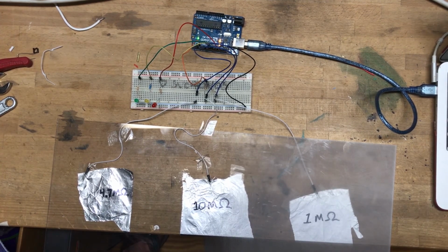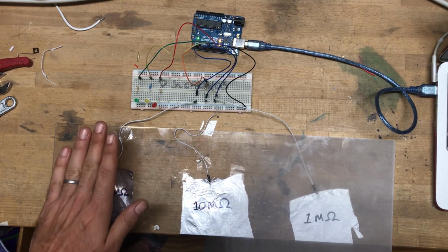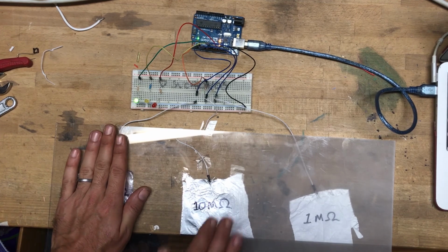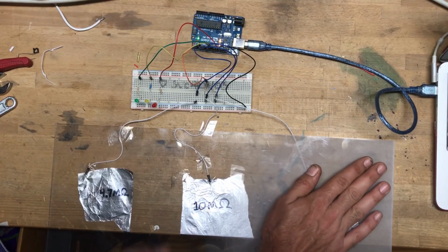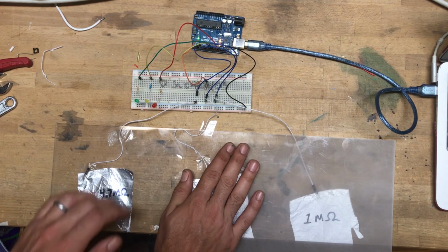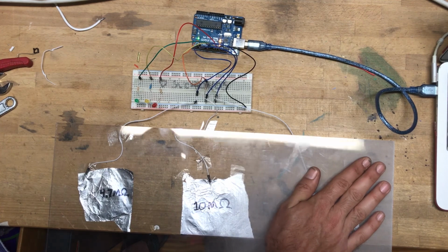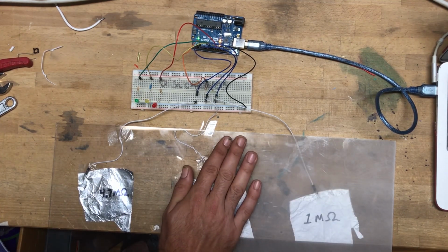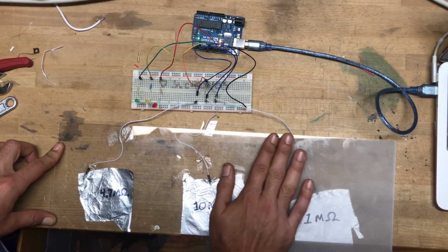So here we have the exact same circuit that we were working with before, except now I've put this kind of scrappy piece of plexiglass over my foil, so I won't be making direct electrical contact. But because capacitance is measuring my electric field, and that electric field extends beyond my body a little bit, and the sensor can pick that up, I don't actually have to make a direct electrical connection. I can be transmitting my capacitance through the plexiglass, which gives you a few interesting different options with how to interact with your objects.